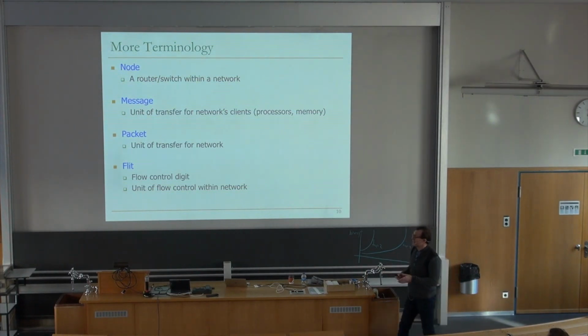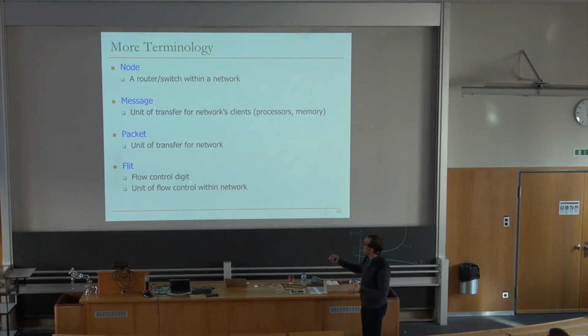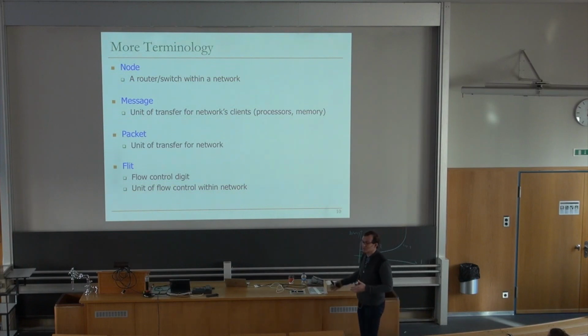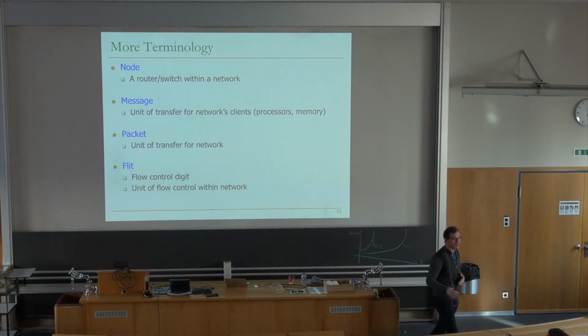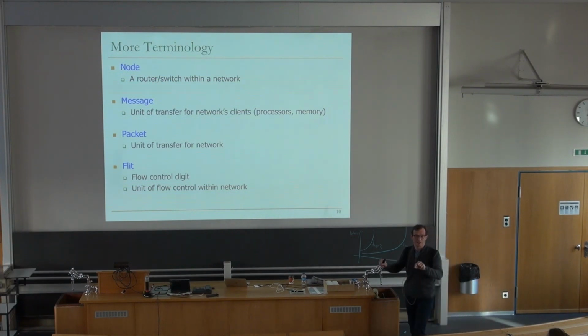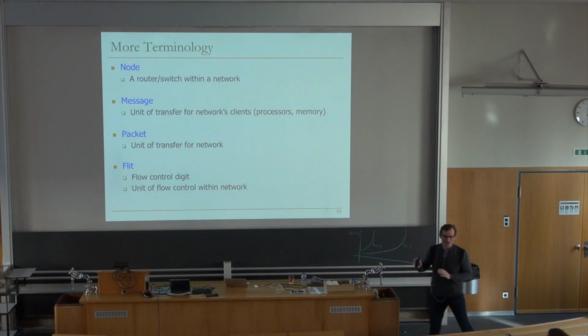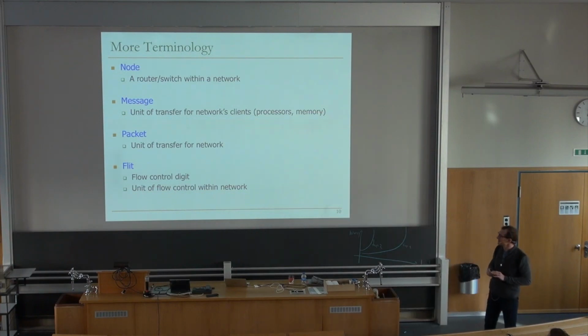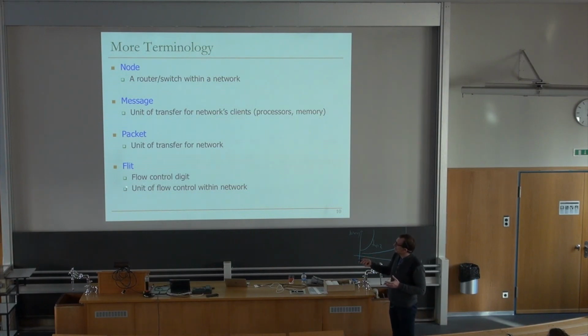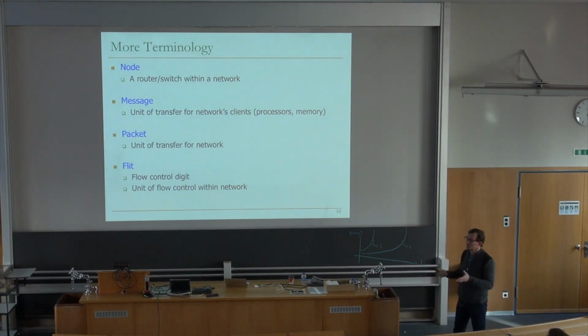And that way you can actually keep your links smaller. For example, your packet may be 64 bytes, but your flit may be 8 bytes, right? That way you can have 8-byte links, and you can send the 64-byte packet in 8 cycles. It doesn't have to be consecutive cycles, because you can interleave those cycles with other flits on the same link. Okay, so that's just some terminology so that you can keep this in mind. And again, you can do the routing at the flit level also, as we will see later on. You don't have to do the routing at the packet level, but you can still have packets.